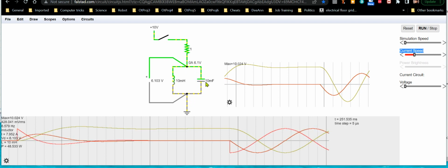You'll see some internal resistances associated with capacitors, like leakage resistance and equivalent series resistance, and inductors always have resistance associated with the wire they're wound on, plus they can have magnetic losses and a bunch of other things that, if you get really into it, you'll see. But again, that's not what this video is about. This video is about understanding the basic concept of this energy exchange and how it works, because it's non-intuitive if you don't understand how these components work.